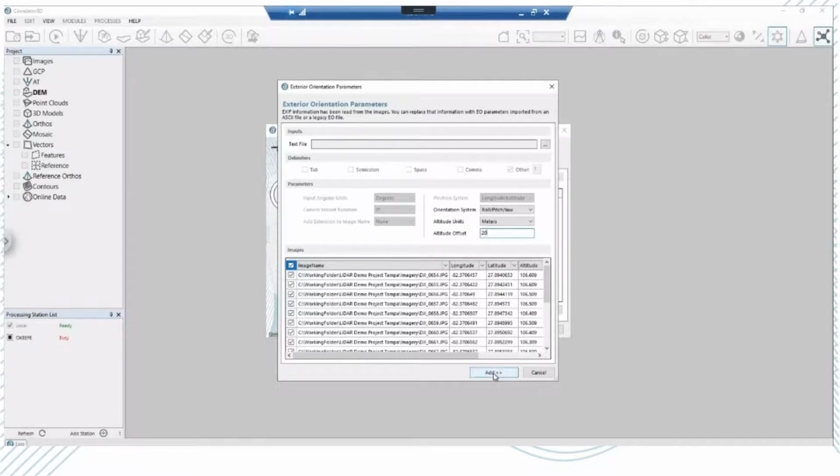And that's the easiest way to account for that offset that we're seeing in between our ground control points, our checkpoints, and typically our imagery collected in ellipsoidal height. And what that's doing is it is adding or subtracting that value, depending on what the situation is, to your EXIF information, to the altitude that's being reported with the drone.